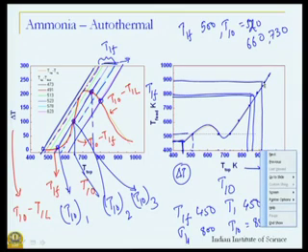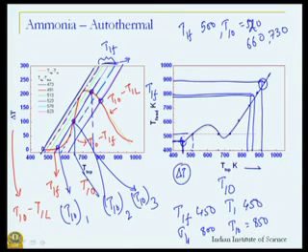So, very little reaction on both these sides, but lot of reaction at these two particular points. How do I know there is lot of reaction? You look at delta T. For example, delta T here, the temperature difference between the inlet and exit is almost 160 degrees with this point. This point delta T is even higher, almost 230 degrees, which is the indication that lot of reaction has taken place.